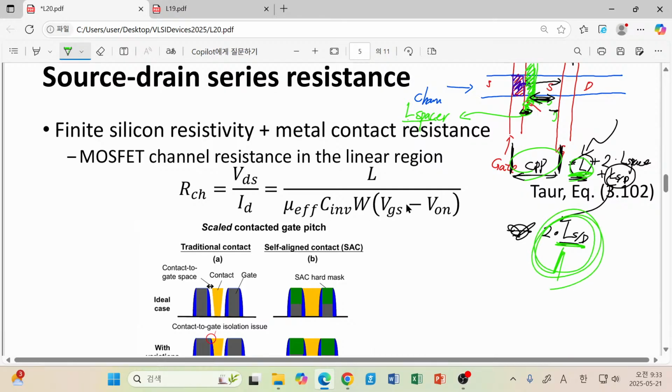So we have enjoyed the reduction of source drain length. But where are we now? Now the reduction of source drain length has really hit the wall, so we cannot reduce it any further. So now people have to come back once again to the real essential question: can we reduce the channel length? Because the source drain did its best and reduced quite a lot, the channel just stays there. Oh, 12, I cannot reduce it further, because then there is a long list of problems, including the short channel effect, shorter than 12 nanometer. So no, I cannot reduce the channel length any further.